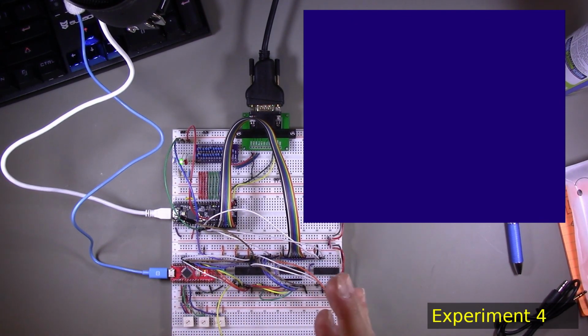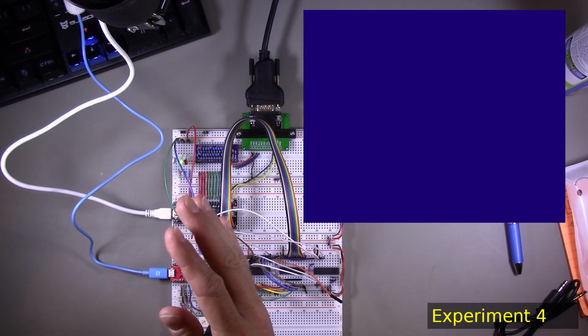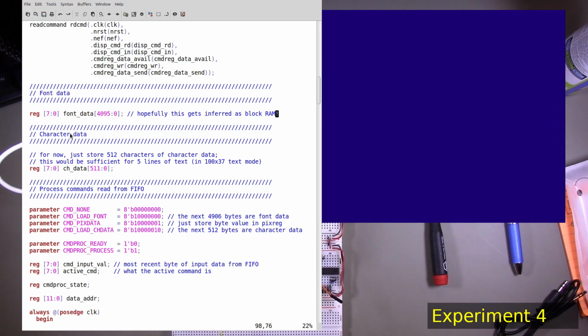So that was all working. I assumed that data was in the FPGA, so all that remained was to actually try to render some characters. One additional aspect of experiment 4 that I couldn't really test fully was whether the font data and the character data would be placed in blockram.